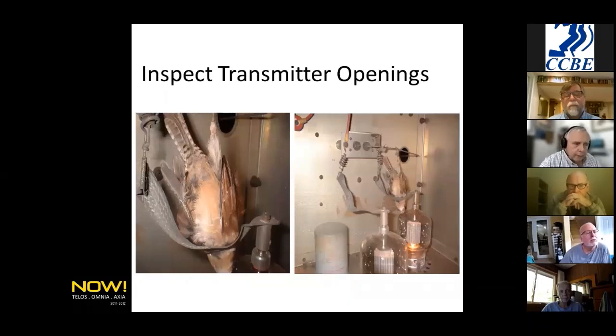Important for you to inspect transmitter openings too. This poor bird got inside a transmitter and got across the wrong contacts there, and the result is RIP. So you want to make sure that your openings in your transmitters are sealed.